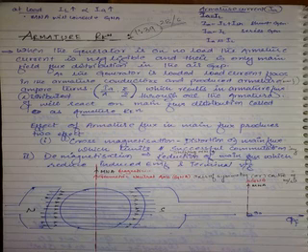When the machine is loaded, there is armature flux in the air gap. Why does armature flux come into the picture? When load current flows through the armature having turns, armature current into armature turns is armature MMF, which gives rise to armature flux, which is in the same air gap. Now, in this 1 mm air gap, there is main flux, there is armature flux. They will interact, they will react with each other, and that reaction is armature reaction.